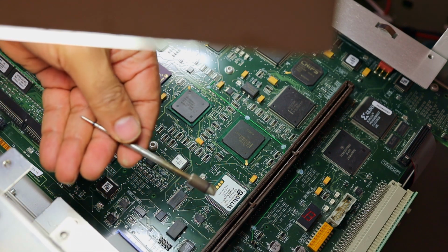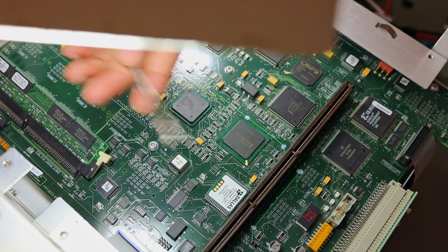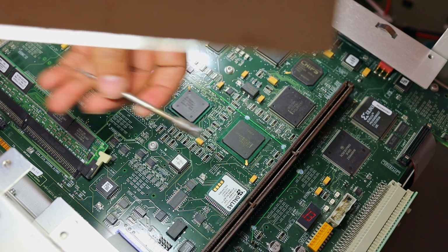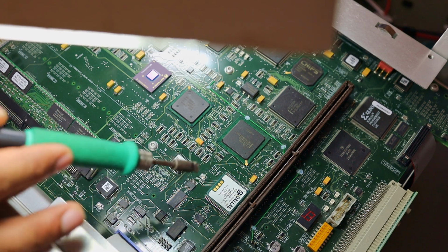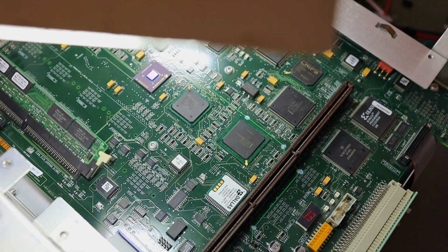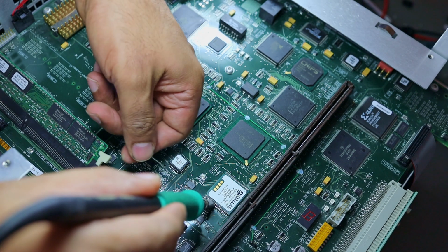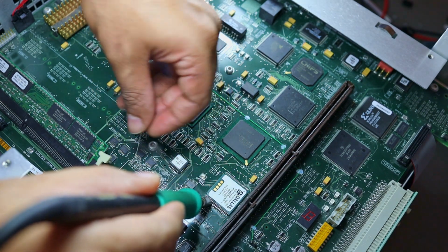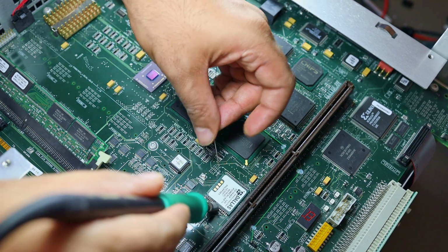I use my thickest tip so that I can cover as many pads as possible. If you have a chisel tip with a long chisel, that can also work. This thick tip allows decent heat transfer as well, and you can touch up many pads. I'll keep the soldering temperature as low as possible. I've set it to 270 degrees. Generally it's quite low for my work. I've put up quite a bit of solder there, so that all the pads have enough thermal mass to keep wet for a long time, and so that I can lift it from one side.